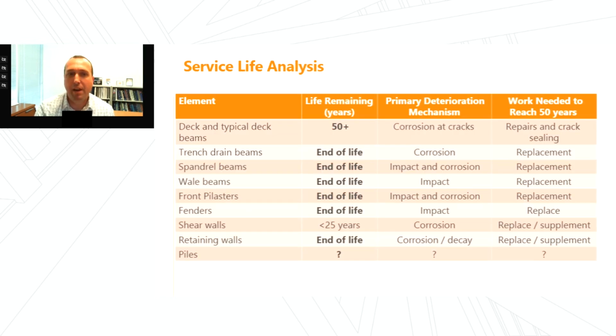So we did do a service life analysis for this particular structure on that approach that Jeff talked about of doing in-depth assessment, performing the laboratory investigation and evaluating the laboratory results. The deck elements and typical deck beam elements that are well above the water, you can see that they have quite a bit of life remaining, and that's consistent with the observations that we had from the visual assessment.